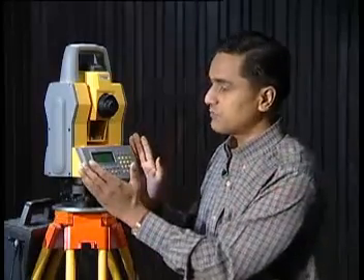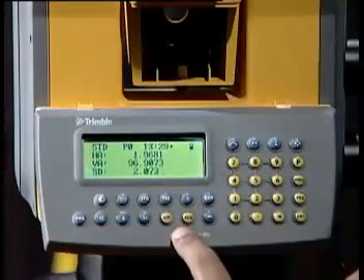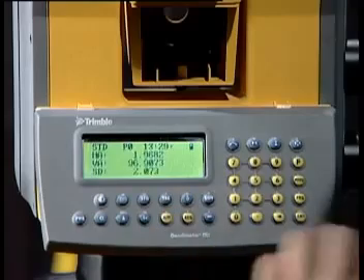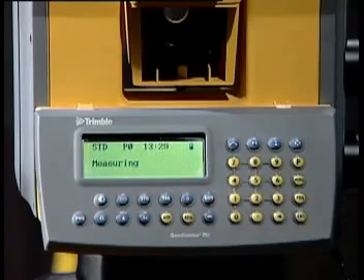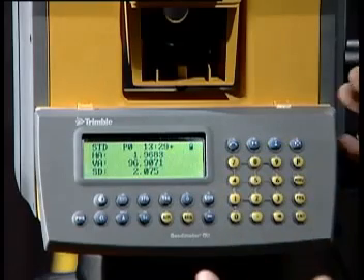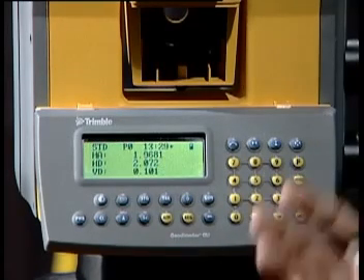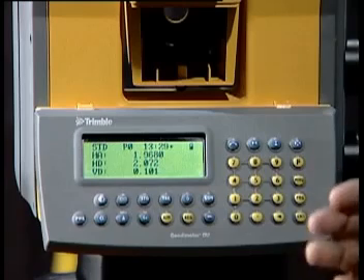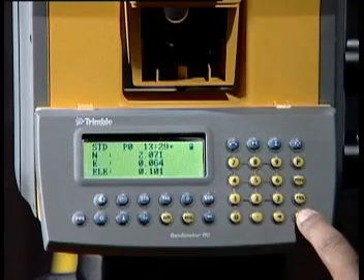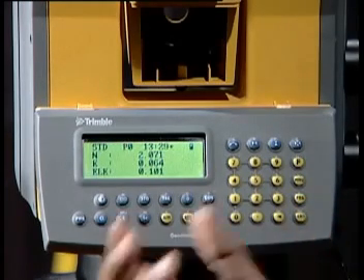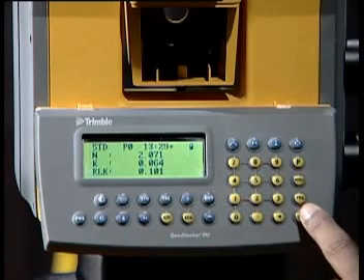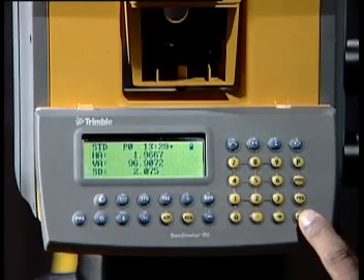Well, after that we come to the panel, and here in the panel we press AM. It starts scanning, then it is doing the measuring, and it gives the sloping distance. So right now the distance from the instrument to the target is 2.075. At the same time, if you press enter, it will tell me some more things. These are the values of the horizontal angle, vertical angle, the easting, northing values, the elevation value, all these are being computed.